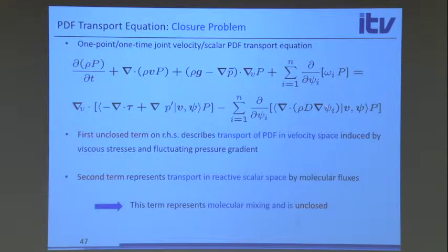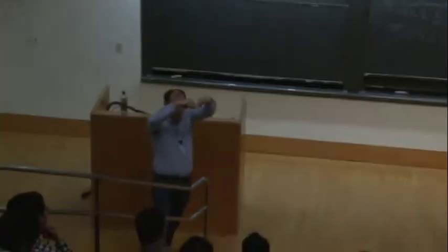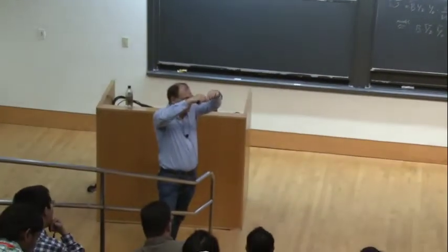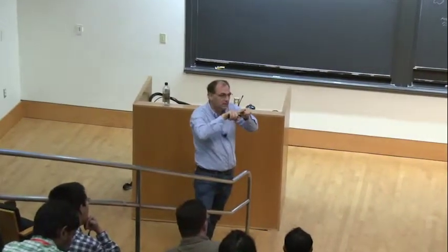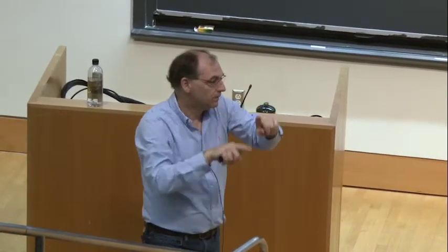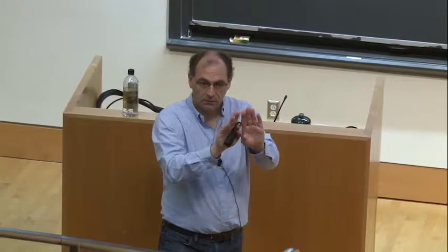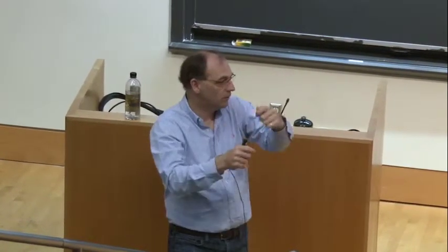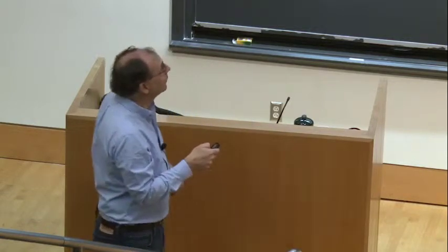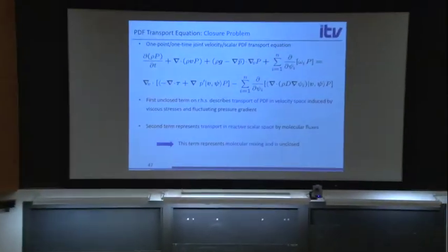And the problem here is now, you see, this needs local gradients. This needs the local gradient of the mass fraction. But in this formulation, I don't have local gradients. I don't know what the local gradient is. I know the PDF of temperature here, and I know the PDF of temperature here. Okay? I know the probability of finding a temperature at each point. But in order to evaluate the gradient, I need to know what's the value here, what's the value here, not the probability. Okay? So the probability can be the exact same on both points, but the gradients are very, very large or very small. Okay? So the gradients I don't know, so this term I can actually not evaluate.